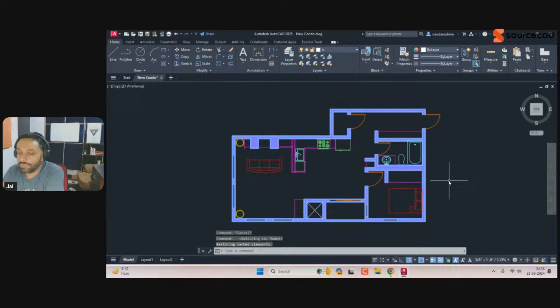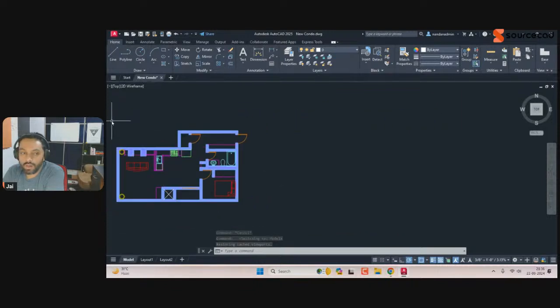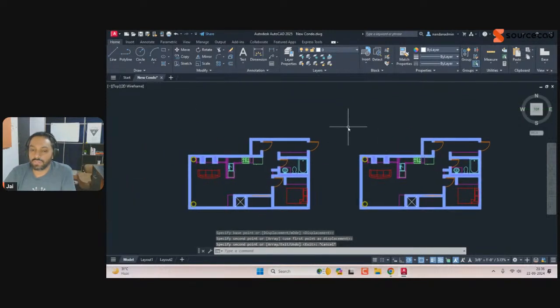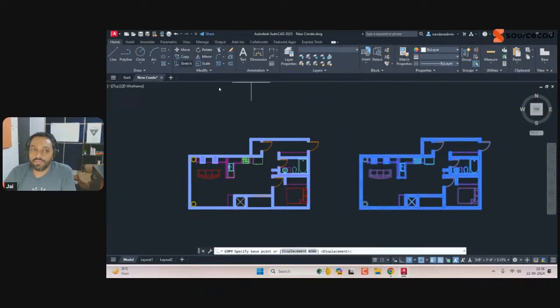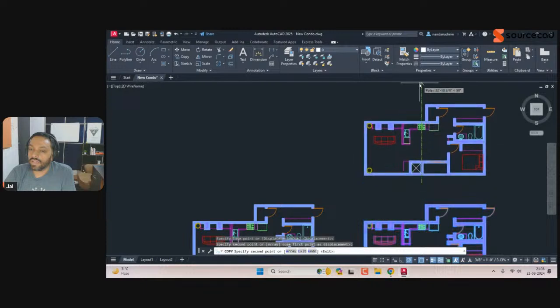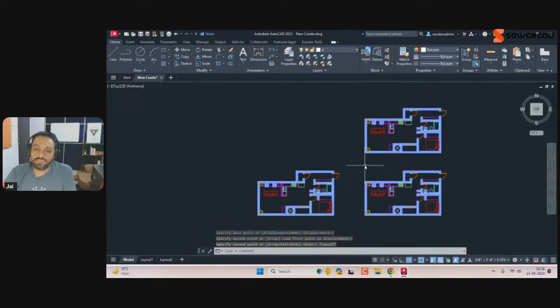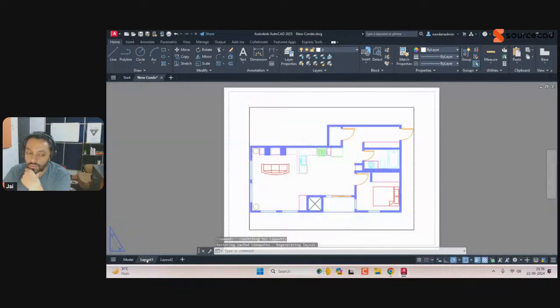So we have made the simple floor plan, then maybe we made a copy, and let's for a moment pretend that this copy is the electrical plan of that house. And then we have another copy, which is the HVAC part, and then another copy again for plumbing and for other things, for structural diagrams and all. So all the details you can just make in model space, and then in layout, you can create specific layouts for a specific part of the drawing.